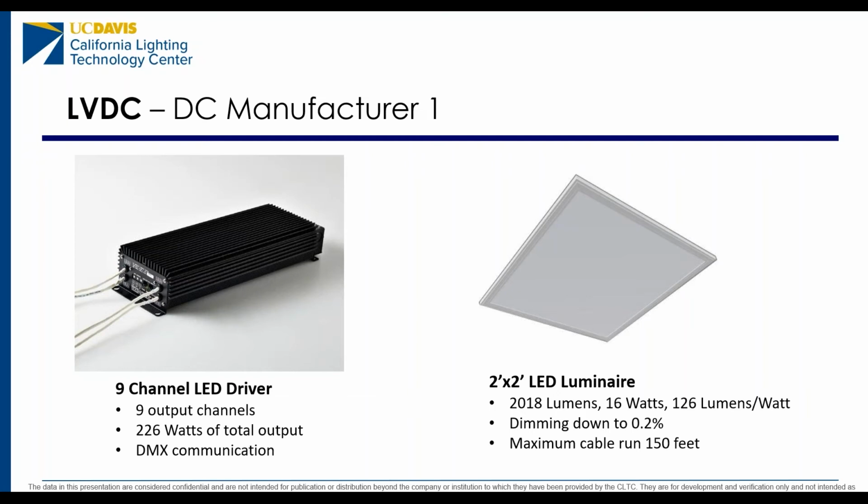They're capable of dimming down to 0.2% and have a maximum cable run between the power supply and the luminaire of 150 feet. Two things to note at this point. When we specified each DC system, we wanted to maximize the load that we could put on the power supply, so we picked luminaires with the highest rated wattage that we could find. And secondly, in terms of system architecture, this LVDC system is the most basic of the DC systems that we looked at, in that it's essentially one centralized driver for 9 luminaires, and that's pretty much it.